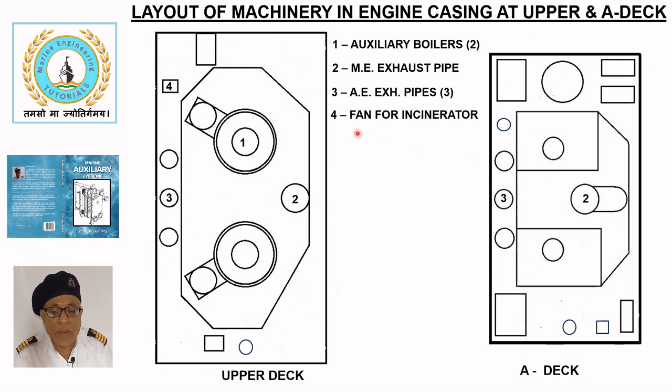The incinerator exhaust fan (4) located on the upper deck maintains a slight vacuum in the furnace to prevent blowback and discharges the exhaust gases to the atmosphere. The waste oil settling tank (5) located on the upper deck receives sludge and waste oils for the incinerator. Settled water is drained off.